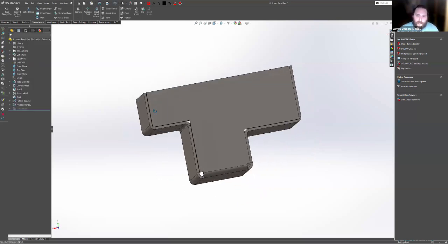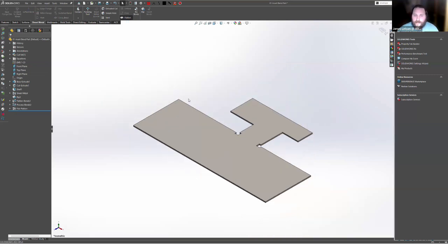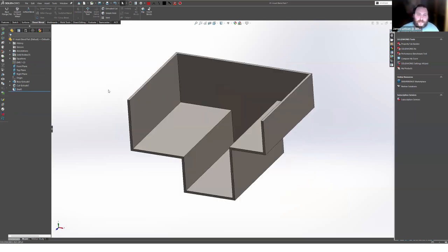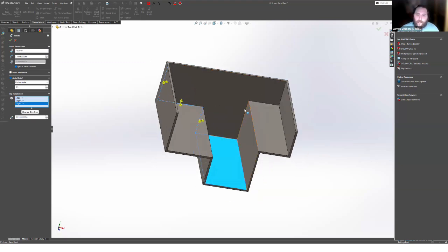And now you can see that we have a sheet metal part that is flattenable, right? The cool thing about this is another little feature in here. Let's just Control Z a couple times and then go do this one more time. Choose my fixed face, choose my ripped edges. And you'll notice as I click these edges here, you'll notice the little yellow arrows that come up.